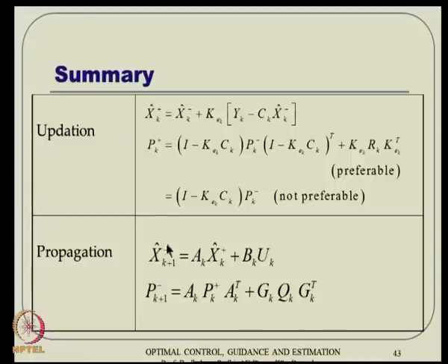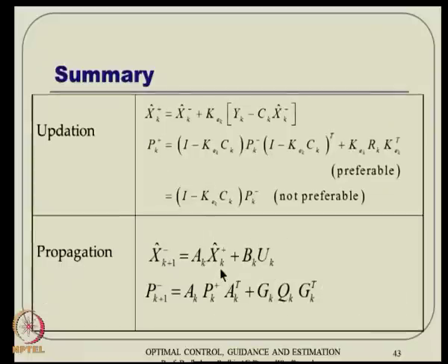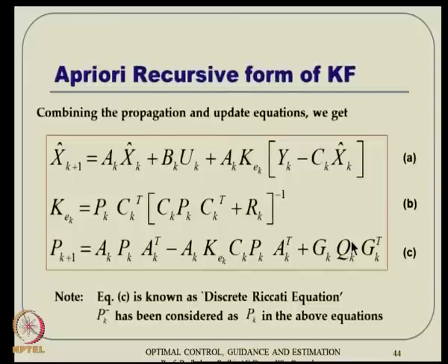So, this is update, then you propagate, then again you go back to Kalman gain, you compute that quickly and then update and then propagate like that. So, that will continue that way. So, this is all about discrete time implementation of the Kalman filter, but some people can also think, okay, we want to implement it in a direct way. In other words, we can also go back and implement the direct recursive form, and there is no point in having minus plus there, because everything happens at the same time sort of thing.